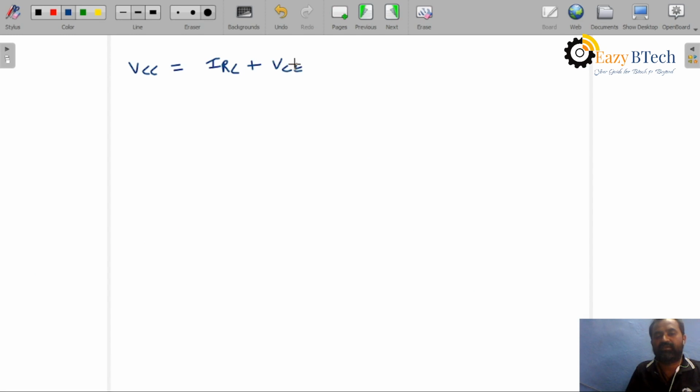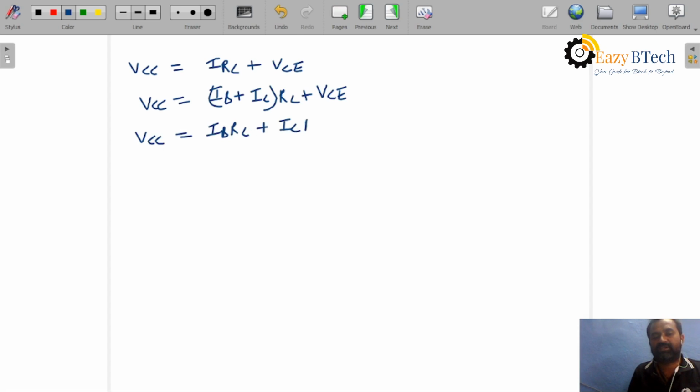Now we already know that I is IB plus IC, so VCC is equal to IB plus IC, into RC, plus VCE. We will write VCC is equal to IB RC plus IC RC plus VCE, the second equation.